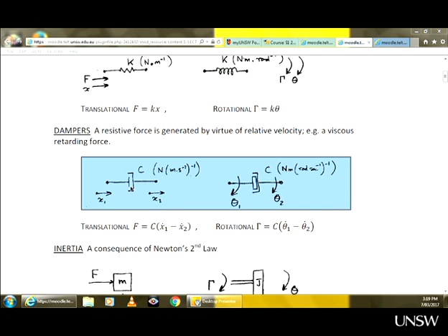And the oil actually flows either through that little hole, or the gaps around the piston are big enough. Maybe I should draw this to explain a bit better, but just at this stage, accept this, that the force in the viscous damper is proportional to the velocity. With the spring, the force is proportional to the displacement. Force proportional to the velocity.